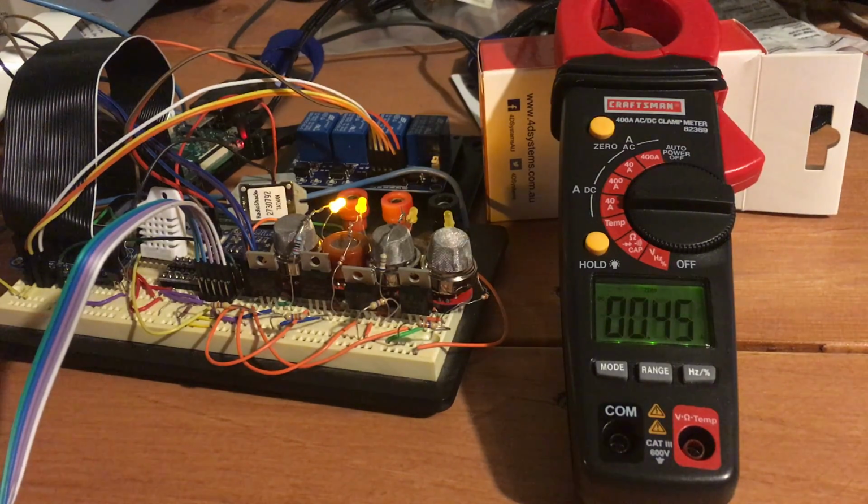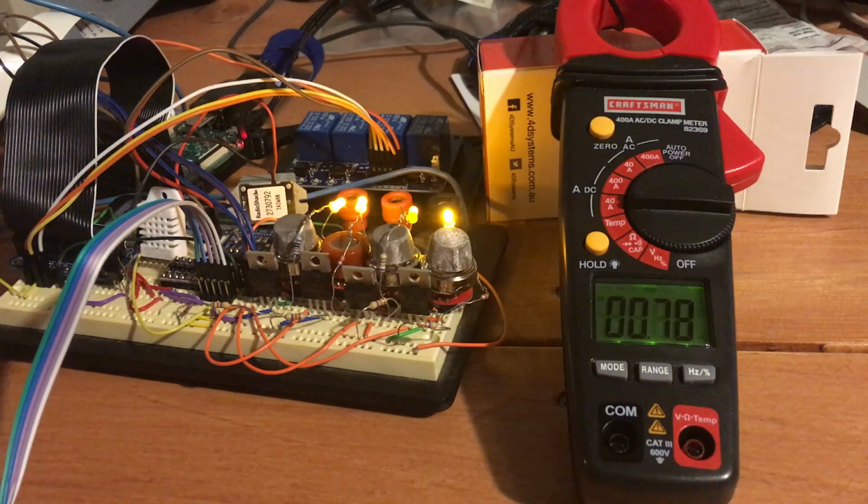So I turn one on and we're up to about 450, whatever, 600 milliamps, 760, sorry, 900 milliamps. So I think I calculated about 200 milliamps per heater circuit, and we're just a little bit less than that, so that's good. So we're at about 900 milliamps at 5 volts.